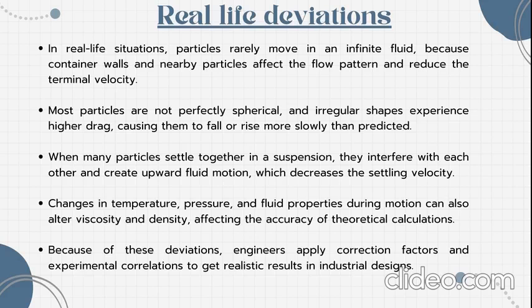This also decreases the settling velocity. Also, changes in the temperature and pressure and fluid properties during the motion of the particles can also alter the viscosity and density, and hence affect the accuracy of our calculations. Because of these deviations, engineers apply correction factors and experimental correlations to get realistic results in industrial designs.